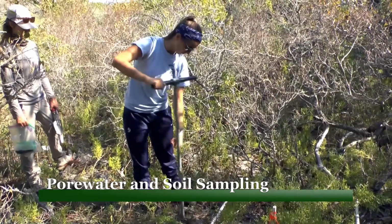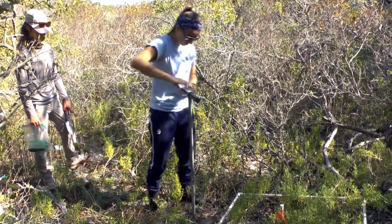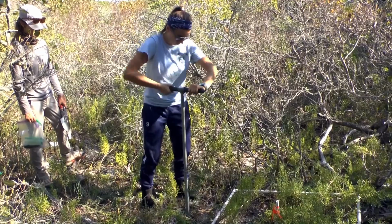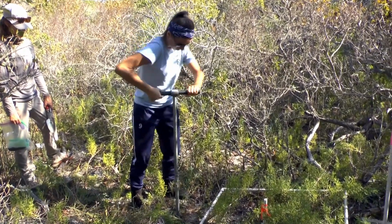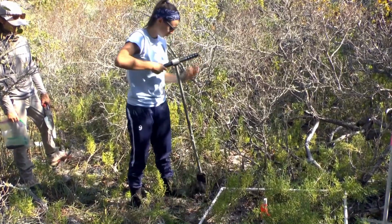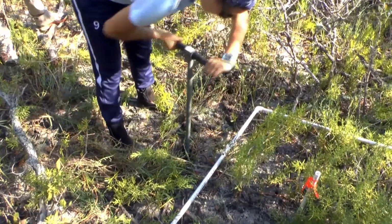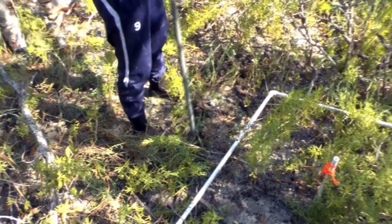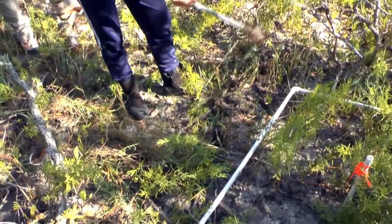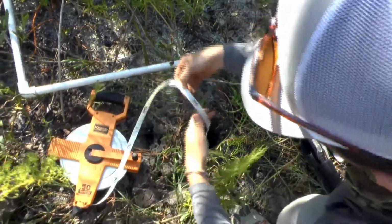Porewater and soil sampling. Sample pore water and soil adjacent to the same randomized plots that were used for feldspar marker horizons. Dig a hole with an auger until you reach the water table. If sediment is relatively dry, you may need to let water percolate into the hole for half an hour before you collect pore water. To improve comparability across locations, pore water sampling should be conducted near low tide for all plots and sites. Record time and date of pore water collection to facilitate tide and precipitation comparisons.